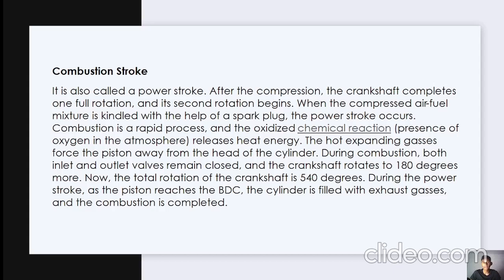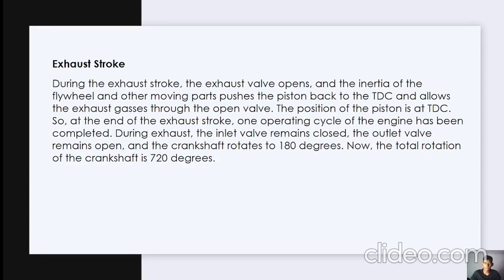During the power stroke, as the piston reaches the bottom dead center, the cylinder is filled with exhaust gases and combustion is completed. Now next stroke is exhaust stroke. During the exhaust stroke, the exhaust valve opens and the inertia of flywheel and other moving parts pushes the piston back to top dead center and allows the exhaust gas through the open valve. The position of piston is at top dead center.